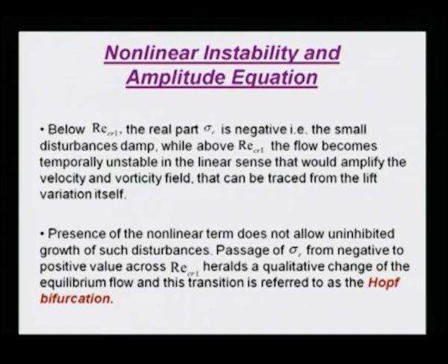The presence of the nonlinear term does not allow uninhibited growth of such disturbances. Passage of sigma r from negative to positive value across Re critical heralds a qualitative change of the equilibrium flow, and this is the formal definition of Hopf bifurcation, which we would be following.